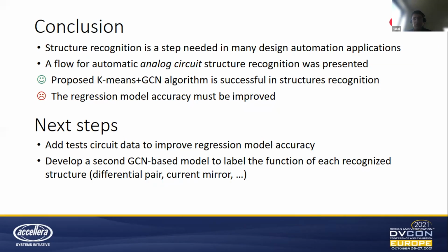The other one is we use an optimization algorithm for automatic circuit sizing. In that case, this algorithm is sequential quadratic programming, and you get much further with this tool if you also define electrical and geometric constraints. So if you know all your devices should be in saturation and strong inversion, right?